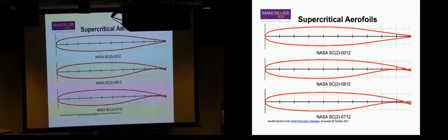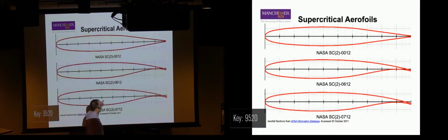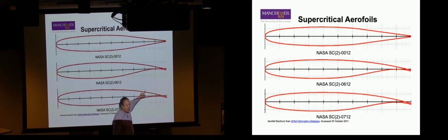So if it goes from Mach, say, 1.5 to Mach 0.8, that's a big step. But if it goes from 1.01 to 0.9 and then goes down to 0.8, that's a much smaller step. That means we get weaker shocks, which means for the same free stream Mach number, we get less drag. So what happens is those shocks develop, they get stronger, our drag goes up exponentially, and we want to delay that. To do that, we put our curvature at the very end, the last possible moment.